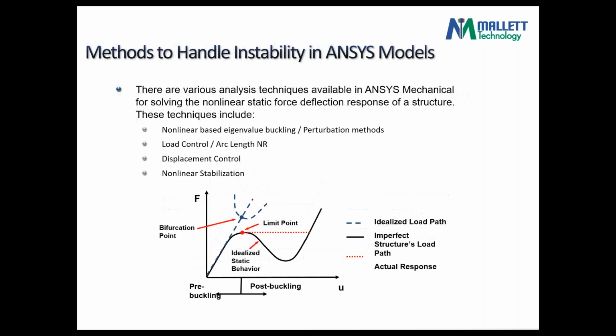What exactly is happening here? Well, we need to tackle this problem in ANSYS. One way to do it, which we did in the old days, is we follow the first method. We predict using this method here. We just do linear analysis, static analysis, and then we look for what shape the structure will take as it bifurcates. You can predict this force by doing what ANSYS calls the perturbation method, or some form of eigenvalue solution, which gives you a critical load.